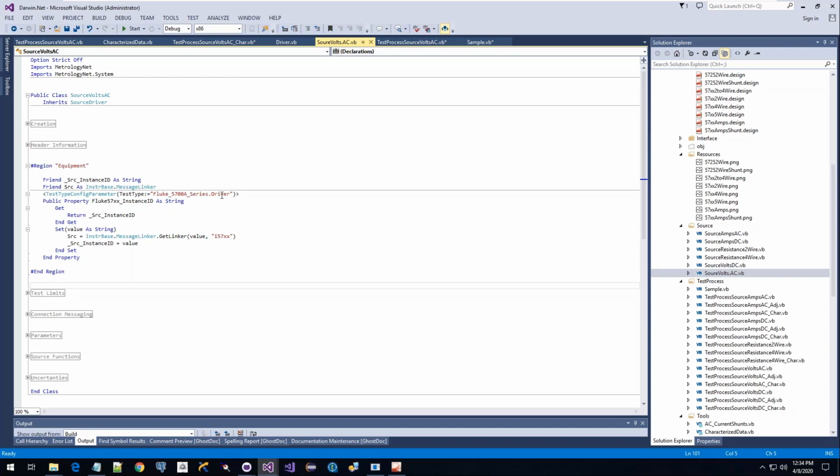Now, I build my drivers in this 3-level stack, so I get reusability of the drivers. And I also get the ability to lock them down so I can run fully threaded calibrations without using the resources at the same time. So an example of the advantage you get out of this layering is that you can have a workstation that's got a 3458 and a 5700 on it.